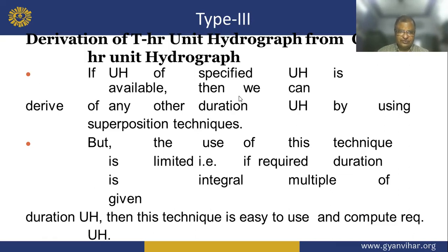If the UH of a specified duration is available, then we can derive the UH of any other duration by using the superposition technique.